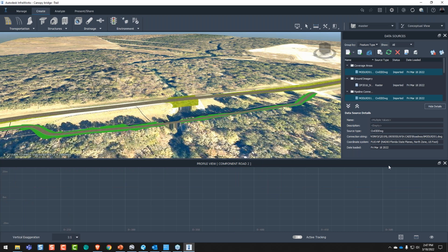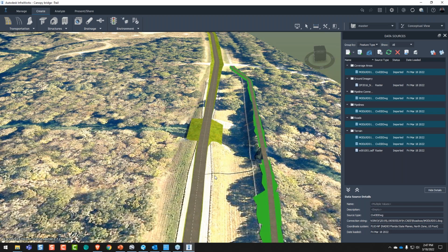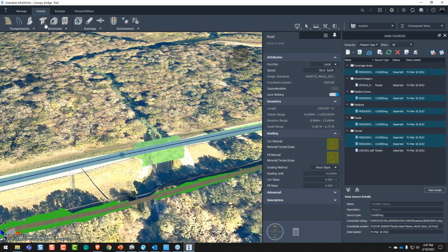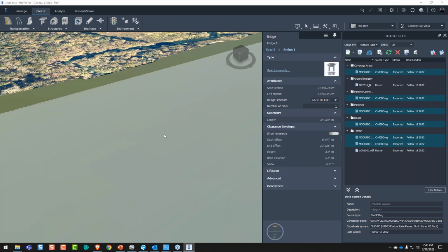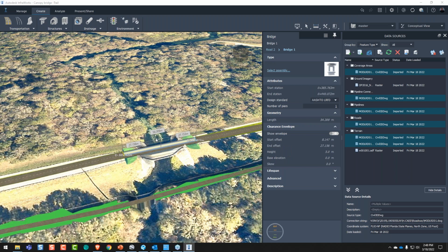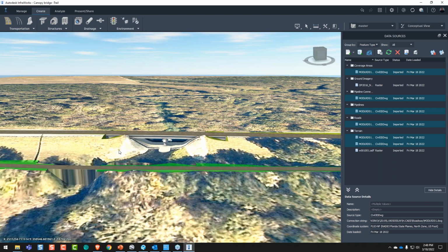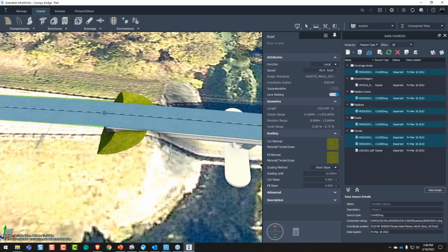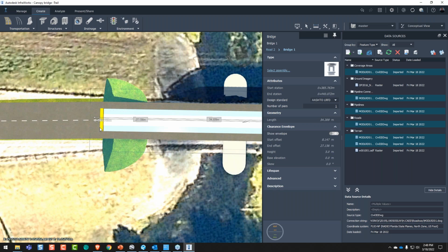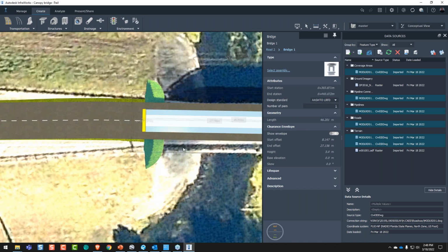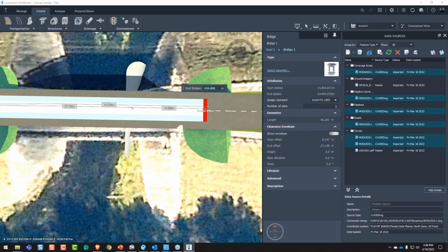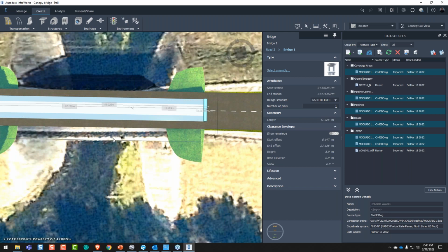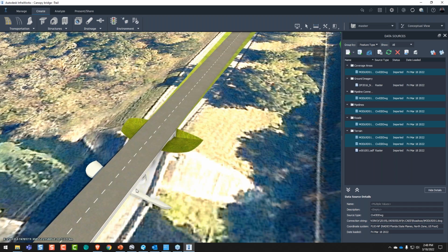Now what I need to do is make a bridge, right? Because obviously that's going to show there. So I'm going to go ahead and start over here and we'll go here, see what it gives me. Again, I don't need to be fancy schmancy here because it's just a visual thing at this point, all right? All right, I'll just hit escape. Right, and there's that. I'll probably pull this in a little bit closer, right? If you click on the bridge, you can pull this back in. Again, InfraWorks is fairly easy to work with. It's not hard. The only thing you'll have to get used to is the zooming is a little different. Right click is pan, left click is rotate view, and middle click is zoom up or down. It's very strange, and you can't change that. No matter how many times you've asked them to make it like AutoCAD, they won't do it.